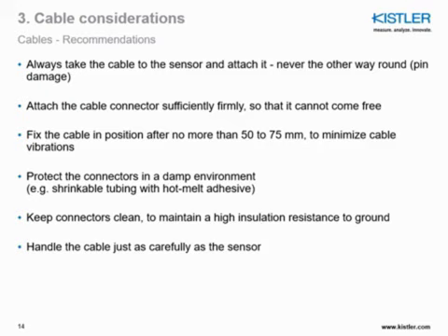Always keep connectors clean to maintain the high insulation resistance to ground whenever we are talking about charge output sensors. In general, connectors need to be kept clean anyway, and handle the cable just as carefully as the sensor.